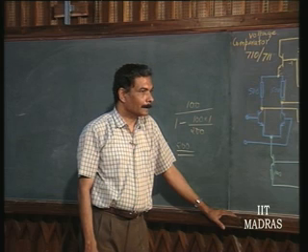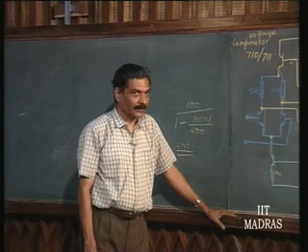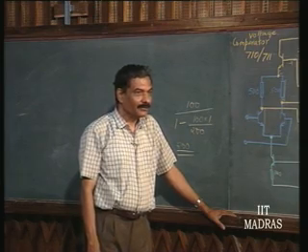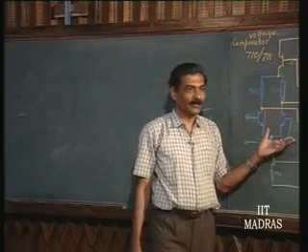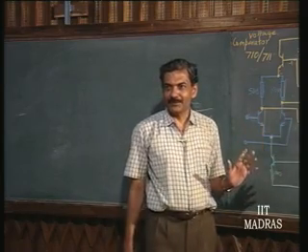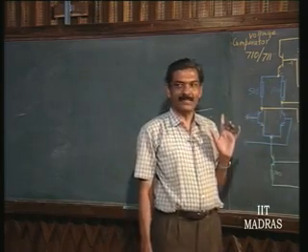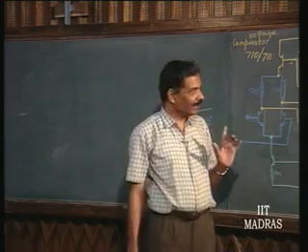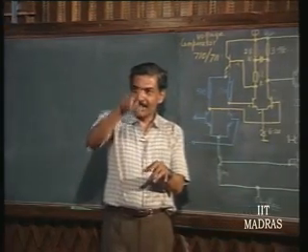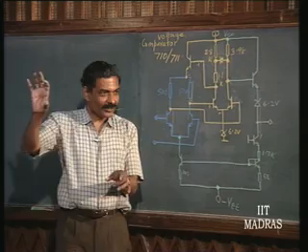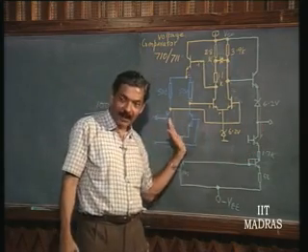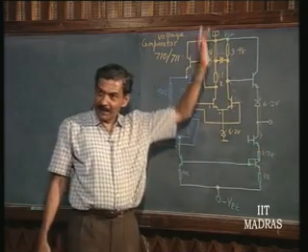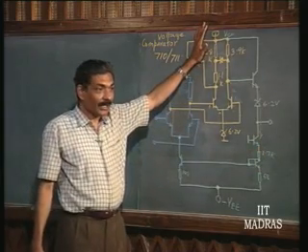Sir, but even if you use negative feedback in this, it's going to behave as a linear device. Yes, but what will be the danger of negative feedback here? It will start oscillating. You can see that also. Even without negative feedback, if your power supply itself is not bypassed properly, you will see that apart from high and low, you will have a thick line on the top and bottom here. Why? Because it is still used in open loop, and it has all the poles coming into picture, and the feedback is coming through the power supply.